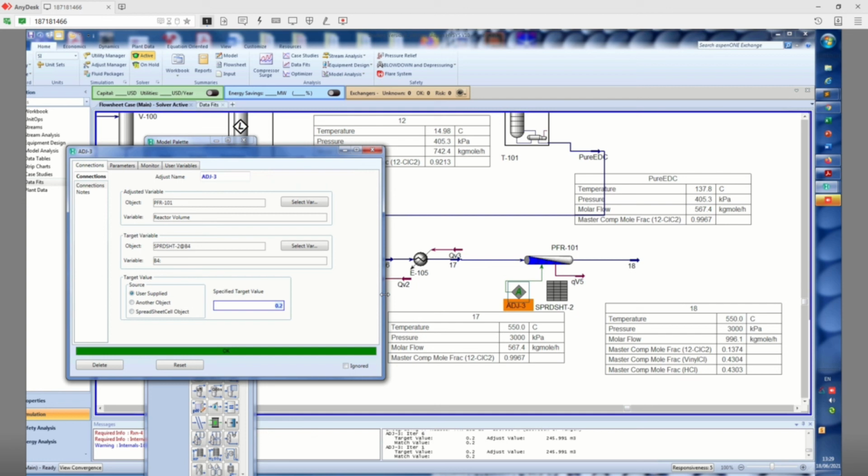How did you solve it? And put a title clearly, like, this is a problem that I encountered when I was designing a Reboiled Absorber. This is a problem which I encountered when I was designing a distillation column, and so on. And these are things which I realized when I was using a continuous stirred tank reactor. I took some rate expression from the literature, and then I added a CSTR, and suddenly I saw there is no product, which means zero conversion. So I deleted the CSTR, and then I went for a conversion reactor, and so on. So these are the things you have to note in your notebook.